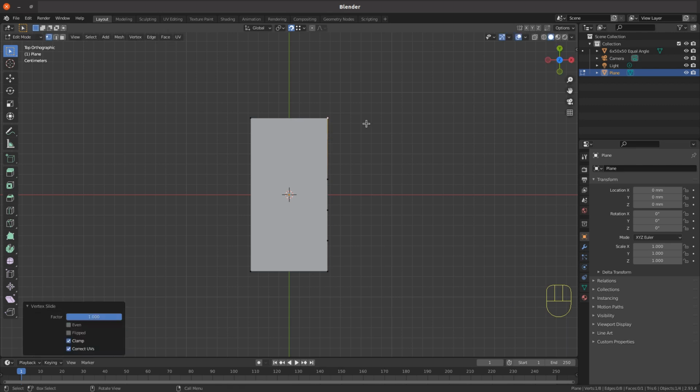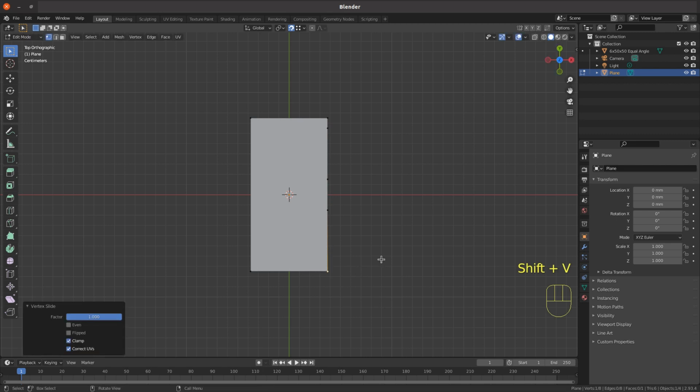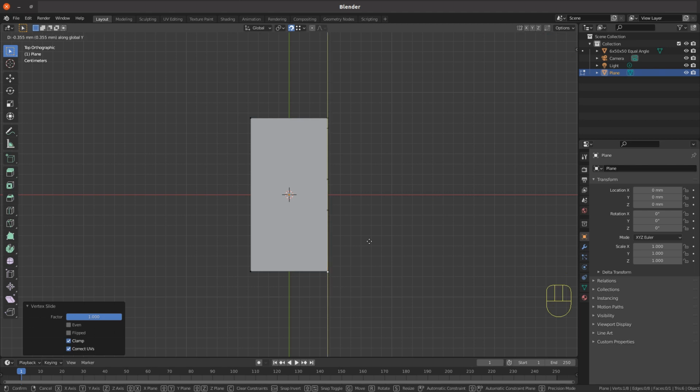We can now move that the 10mm of the flange thickness. So we'll again grab that vertex while it's selected on the y-axis and we'll move it minus 10mm. And do the same for the second from bottom vertex. Left mouse button, select the vertex. Shift V for vertex slide and drag it to the bottom. Then G to grab the vertex on the y-axis and move that one a positive 10mm on the numpad. So number 10 on the numpad, and enter.